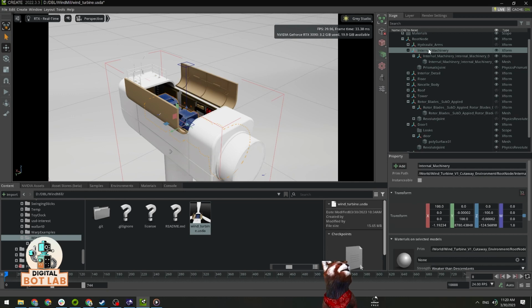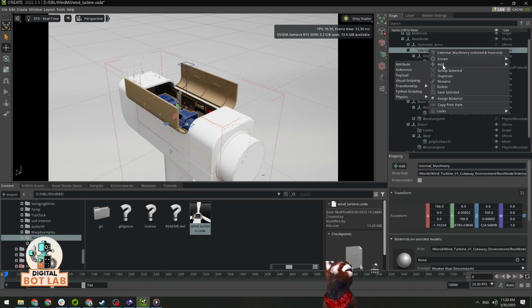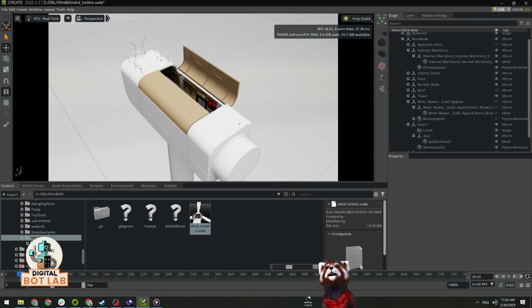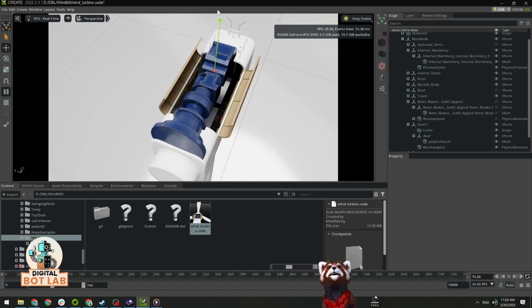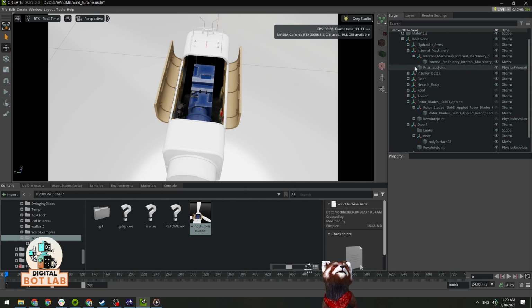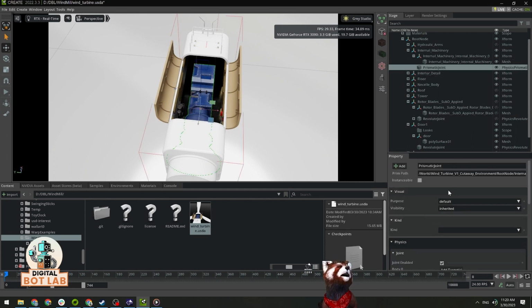And we need to add physics rigid body with collider preset to it as well. And this time we can drag it up from the linear joints. Okay, and we can also add a linear driver to it by clicking the prismatic joint, add physics and linear drive.